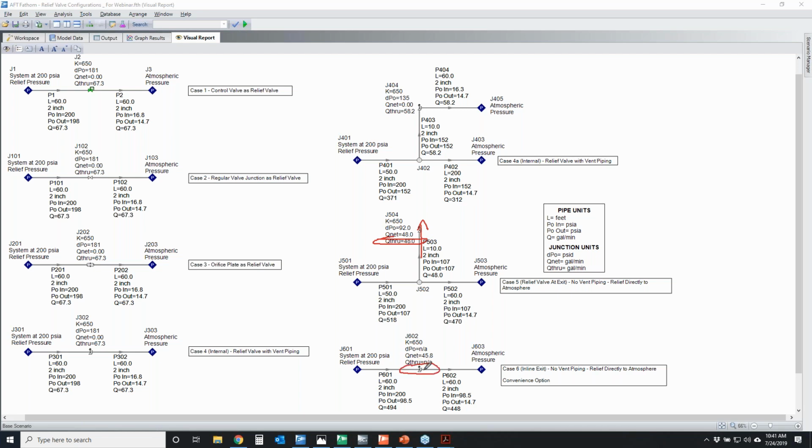But in this system here, what do we mean by the word through? Well, the answer is it's ambiguous. You have flow through the relief valve into that path, and then you have flow through the relief valve into the atmosphere. So does this through represent either of these or a combination of them? It's ambiguous. So that's where you have to find another parameter.